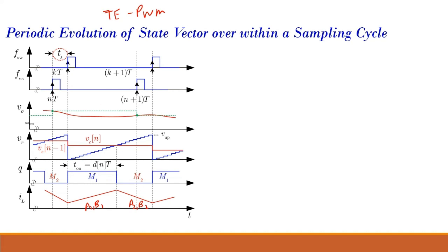Okay, so I take the sample slightly with a delay, considering the delay which we have discussed. I take the sample at delay TS, over here. After I take that sample, it is still in mode M2, still in the off mode. So this is my xn. From xn, it will reach x1 where mode 2 finishes. Then it will go to mode 1, and at the end of mode 1 I will denote it as x2.